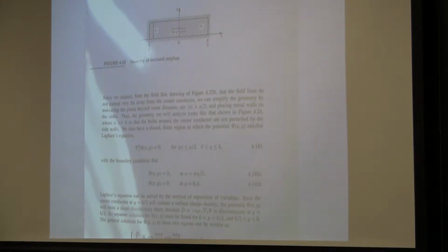From what we know from transmission line theory, which applies here very well because we're simply talking about impedance matching, the input impedance here is related to the parameters here as well as the termination impedance here. So we can work this one out.